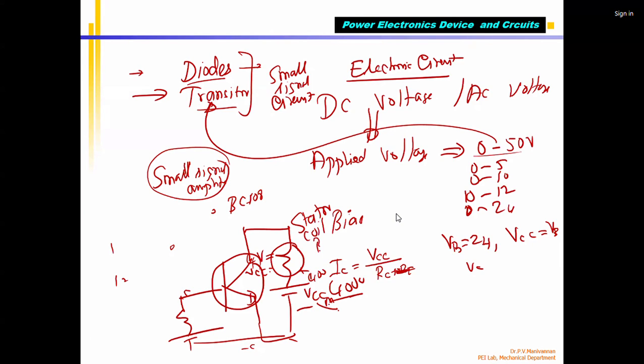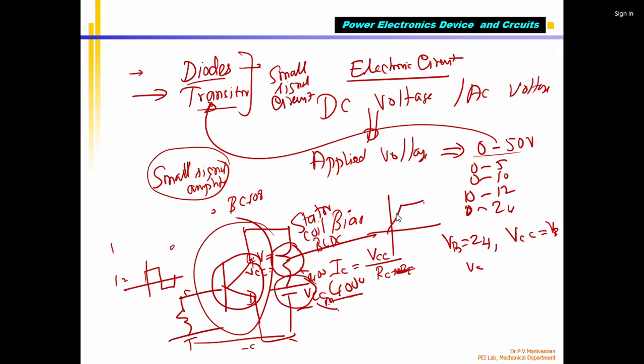For example, maybe a BLDC motor. I am supplying a DC voltage. Of course, in between you have a power electronic circuit. We will be supplying 400 volts to the motor coil, and the motor coil current will be controlled by this. And here I will give a square wave to the base, so that the current flowing through this will be a square wave or trapezoidal wave.